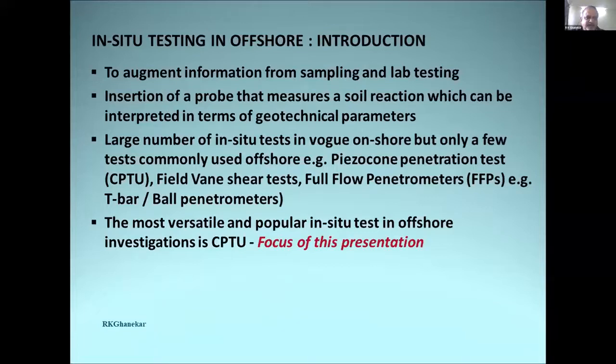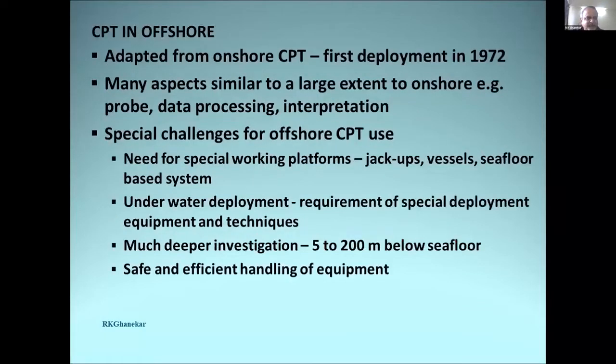A large number of in-situ tests are in vogue onshore, but only a few tests are commonly used offshore. One is the piezo cone penetration testing, CPT or CPTU, and the field vane shear test, and full flow penetrometers like the T-bar or ball penetrometer. The most versatile and popular in-situ test in offshore investigations is the CPTU or the piezo cone penetration testing, which will be the focus of this presentation.